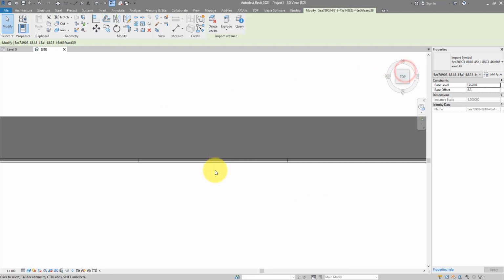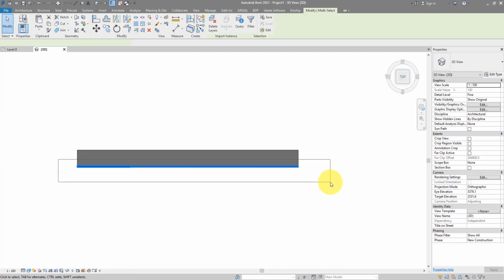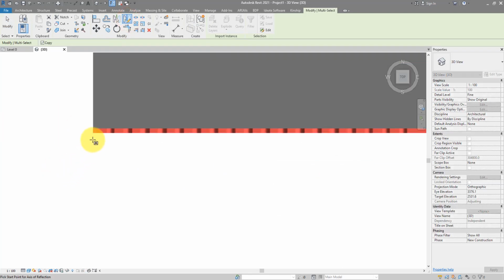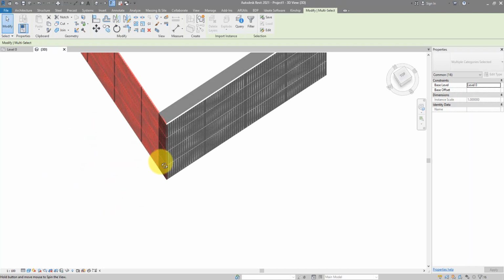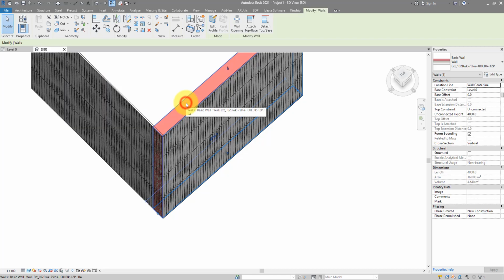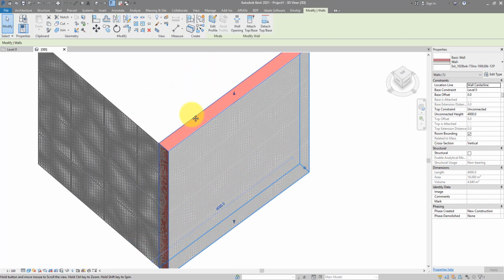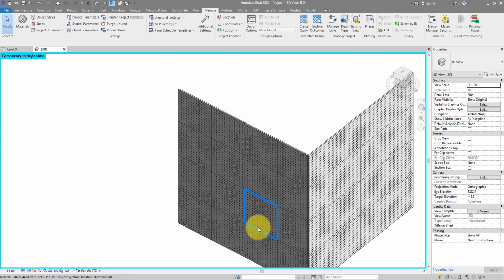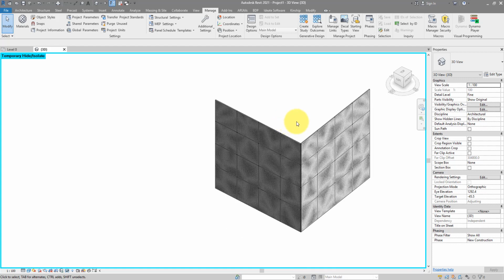Let's go to the top view, select those panels there, and for this I will just do a simple mirror. Maybe against this corner there. And that gives you two faces with perforation panels. Of course, you can repeat the same Dynamo script on this side with another surface, either a wall or something else. But I would only do that if the pattern on this face were different. Otherwise, why not save some time and just copy things around?